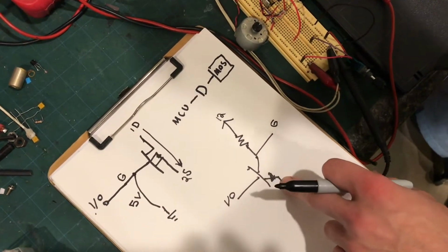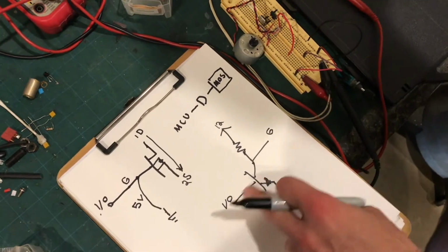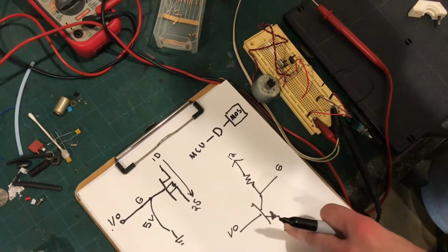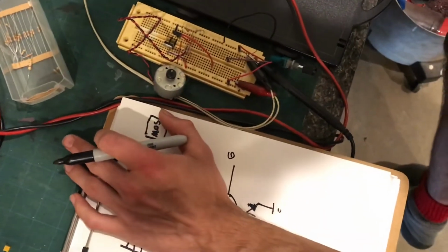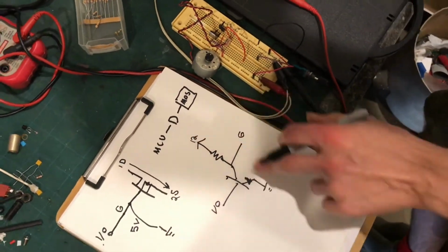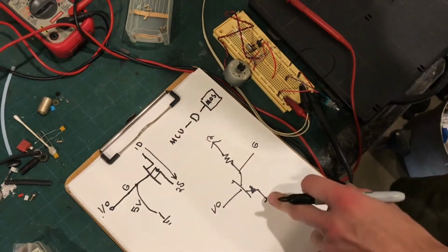And then whenever the transistor is activated by the computer, it shorts this pin to ground, and now the gate is driven to 0 volts. So the gate will either be 12 volts or 0 volts instead of 3.3 volts or 0 volts, which is good.